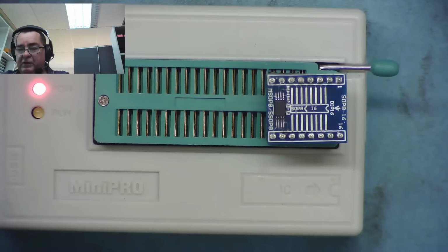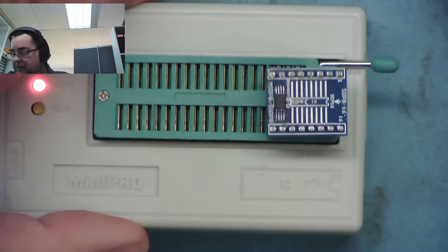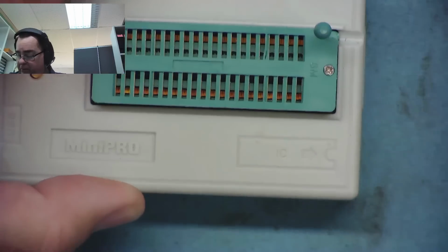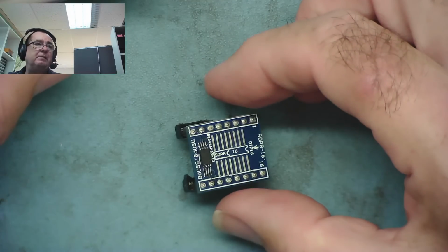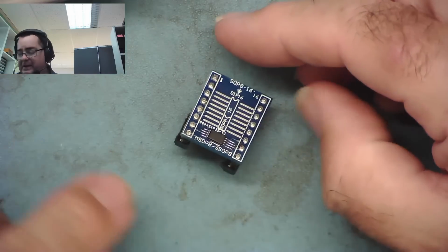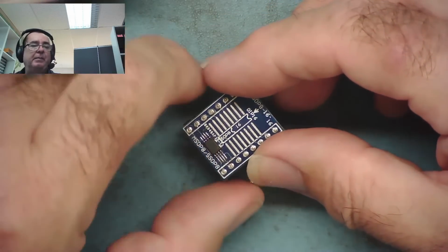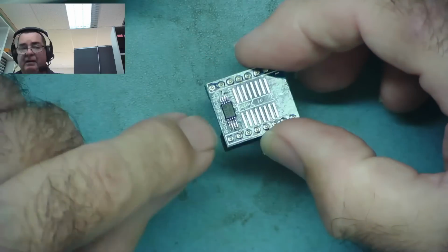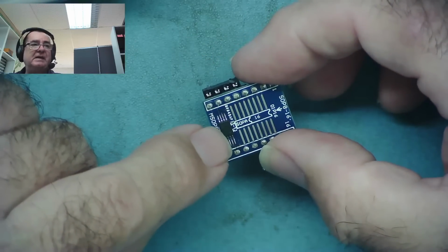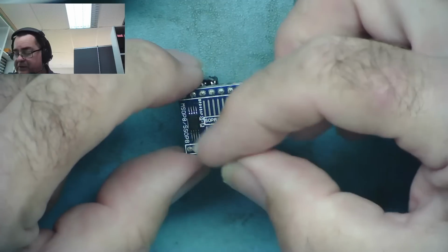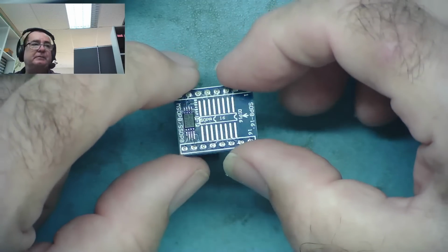I originally used the other one, the spare one, and when I tried to read it in the program, I couldn't read it. And I figured out after a little while that the reason I couldn't read it, this is the little adapter, so I've soldered the EPROM. And it says here that it's MSOP, that's the package type, and it goes here. But in the list of devices, I have this device, the correct device, but only TSOP, which is a slightly bigger package, but the same device.